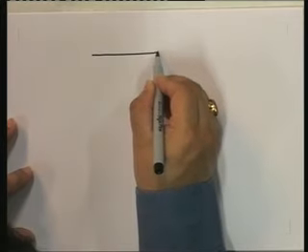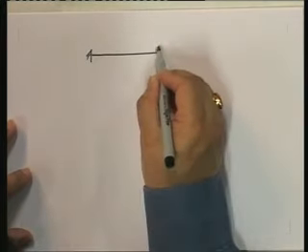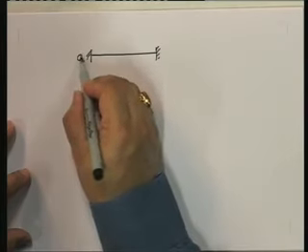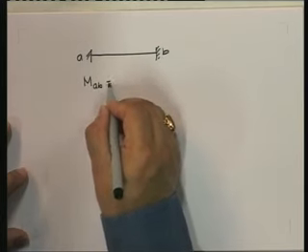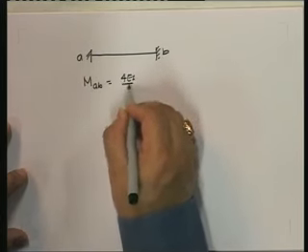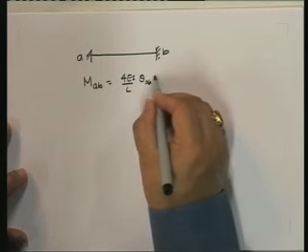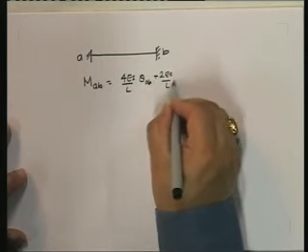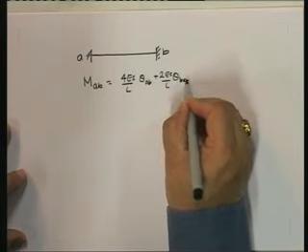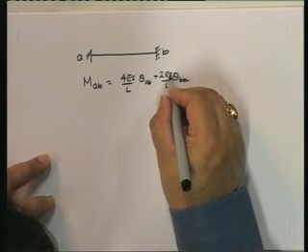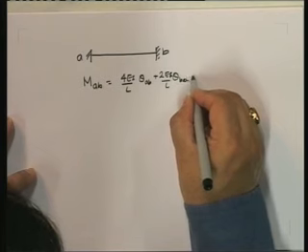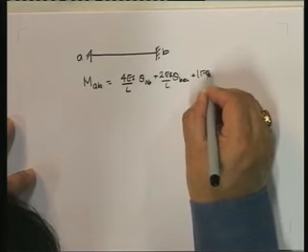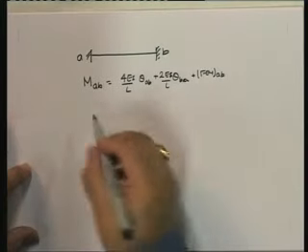So what we are going to do is consider AB as fixed. As far as AB is concerned, we are going to say MAB is equal to 4EI upon L theta AB plus 2EI by L theta BA. Note that since there are no displacements, I am not even writing down the delta, because the chord, or you can say take it from the chord, it doesn't matter, plus the fixed end moment at AB,